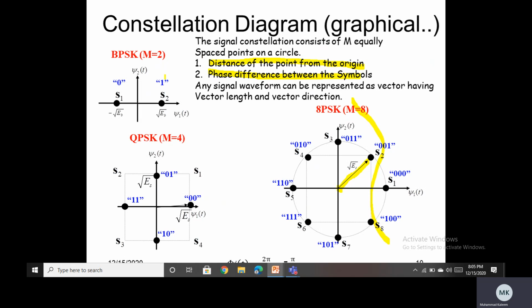So in case of BPSK, the vector picture illustrates the two 180 degree opposing vectors. These vectors are also called antipodal signal sets. So one can see 1 is represented with square root of Eb and 0 is represented with minus square root of Eb, and the phase shift between these two symbols is 180 degree. And you need only one basis function to represent that. And keep in mind, because it's BPSK, 1 bit per symbol, so we talk about bit energy Eb.